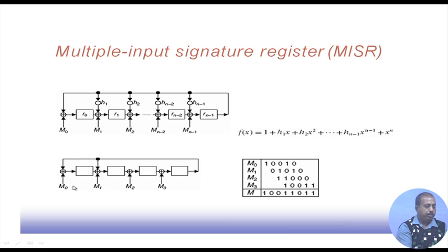Now, if you trace through this operation, in the first cycle, initially all these contents are 0. Now, M0 is 1, so this cell will get a 1 after the first cycle. Then after the second cycle, M0 is 0, and it will depend on what value comes at this point. At this point it is 0, so 0 is coming here, and this will again get a 0.